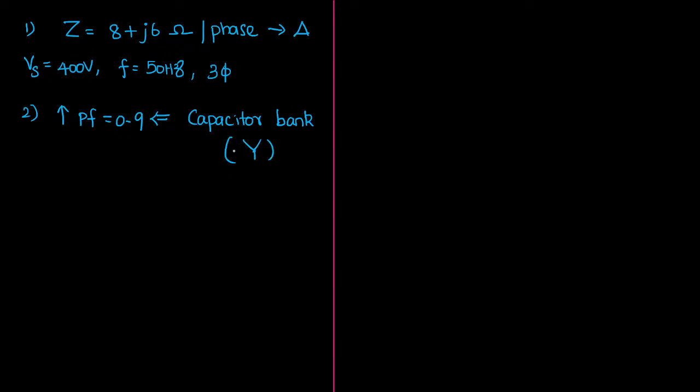Now the required kVAR, it means here what is the amount of kilovolt ampere reactive power demanded by the capacitor? This is the question. Basically, capacitor will be consuming leading reactive power. We all know. So this is the given question. So first step, find the existing reactive power. What is the actual reactive power and power factor offered by the circuit?